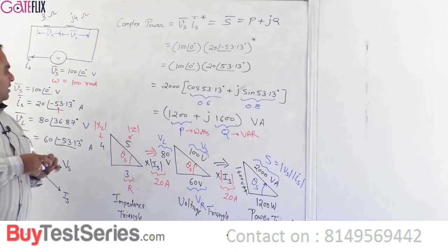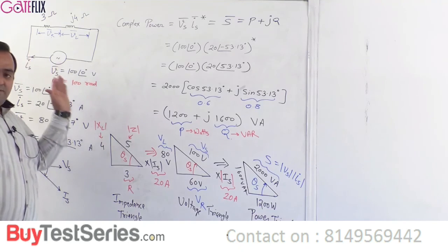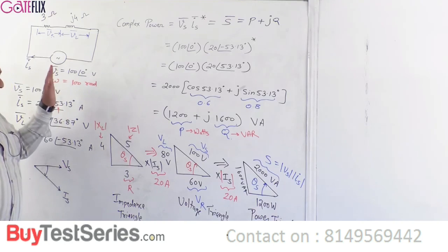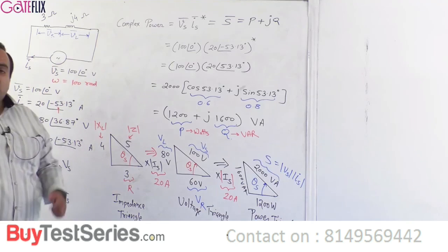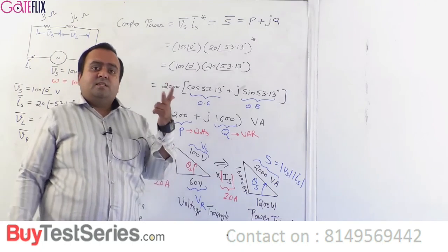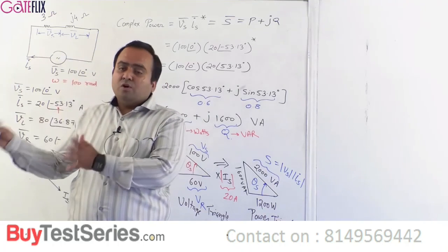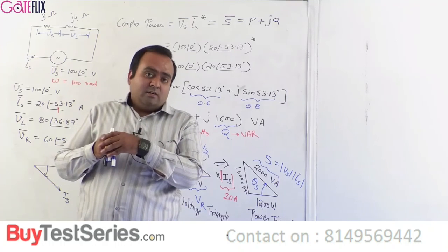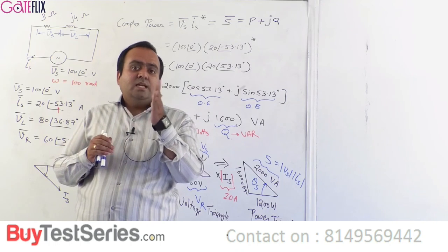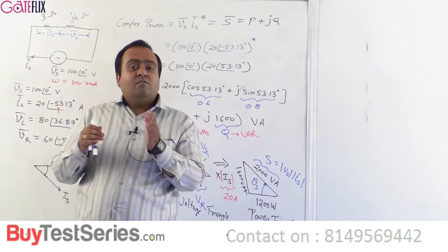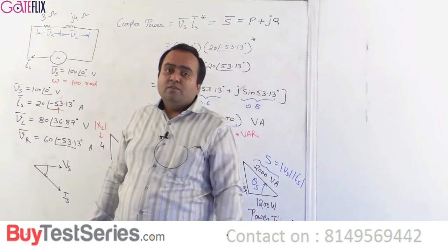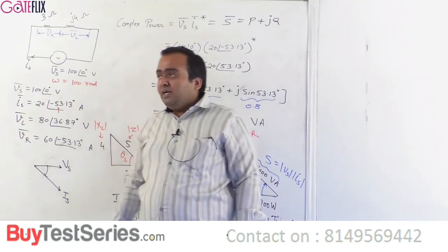Is this okay? So this is how for this one particular circuit we can do these many calculations. Is this okay? So these are called complex calculations. So we have seen how we can calculate the voltage phasors, current phasors, and represent them on the diagram. The basic fundamentals have to be always followed. For an inductor, the current will lag with respect to voltage by 90 degrees. For a capacitor, the current will lead the capacitor voltage by 90 degrees. For a resistance, the voltage across the resistance and the current flowing through it will always be in phase. Why do we take this conjugate?